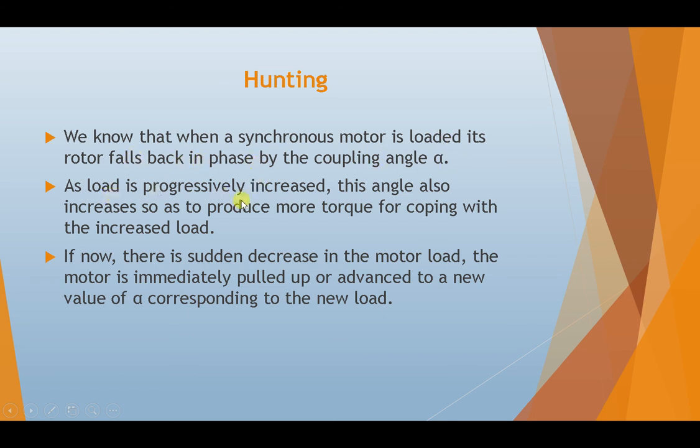As load increases, this angle also increases so as to produce more torque for coping with the increased load. If there is a sudden decrease in the motor load, the motor is immediately pulled up or advanced to a new value corresponding to the new load, that is a new angle.